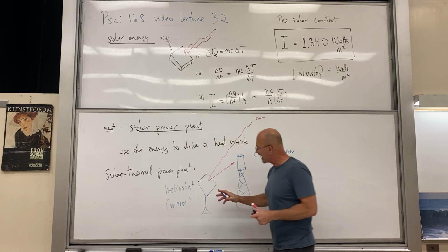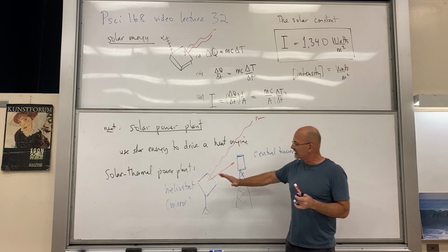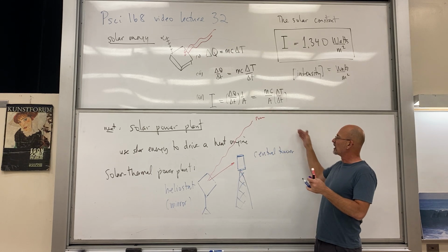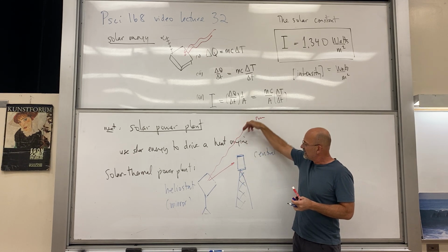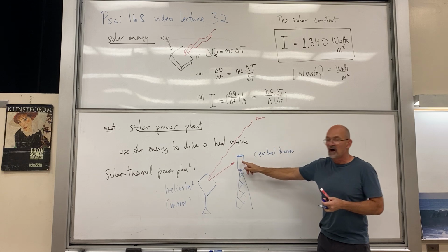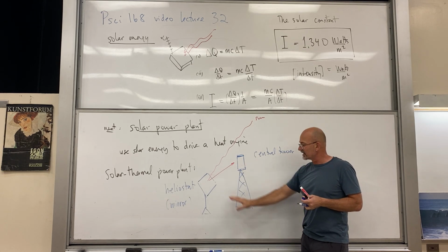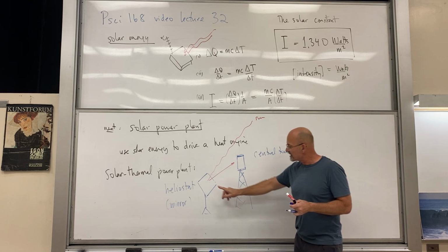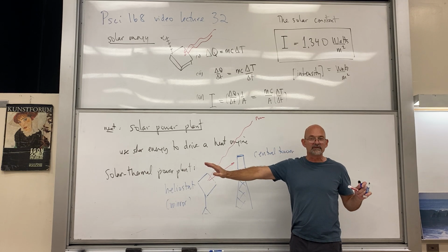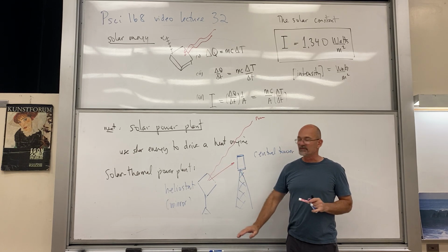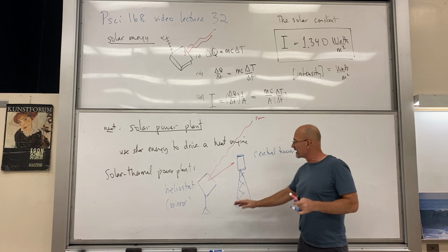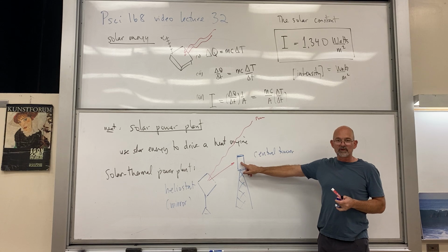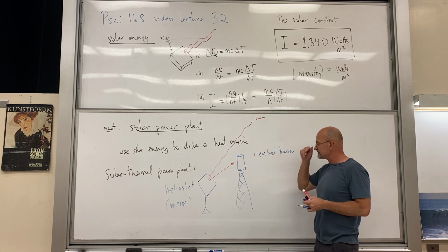And this mirror has to be motor driven because the angle of the mirror tilts throughout the day, so that as the sun goes across the sky, the reflection is always onto the central tower. Okay, so the heliostat is a driven, controlled mirror, and there's not just one, there's an entire field of them, much bigger than a football field. An enormous field of them. All the rays are concentrated on the central tower, which becomes enormously hot.